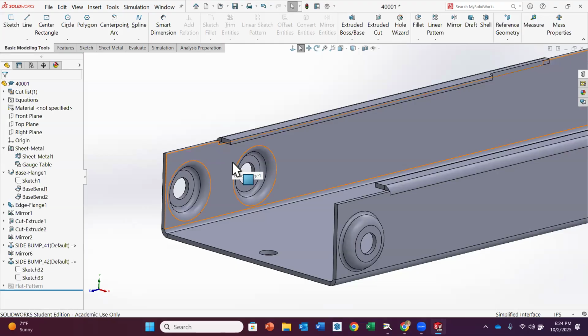I just brought it in first, put it in just a generic place, and then I hit OK, and then I went back in and I went into that second sketch and defined the insertion point, okay? I just found that if I did it on the position tab, it just wasn't working all the time. So I was struggling with that. So that is everything that I wanted to touch on the assembly, the individual parts, as well as pulling in this form tool and the things that you have to keep in mind.